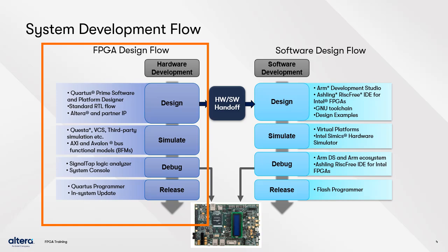Once the hardware system is created, for testing it and functionally simulating it, the bus functional models supported by the Platform Designer system will make that easy. For IP verification, you can use FPGA tools such as Signal Tap Embedded Logic Analyzer or System Console. Those tools can also be used for an SoC development environment as you normally would in an FPGA system.